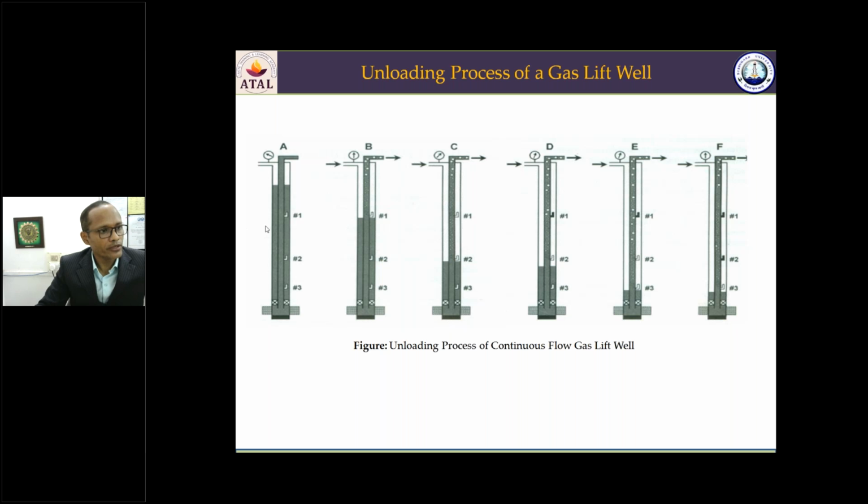annulus. So removing the fluid from the annulus is called the unloading process. In the unloading process, we are removing the fluid from the annulus so that normal gas lift operation can proceed. So these uppermost valves are used for unloading the well. So this is the unloading process.